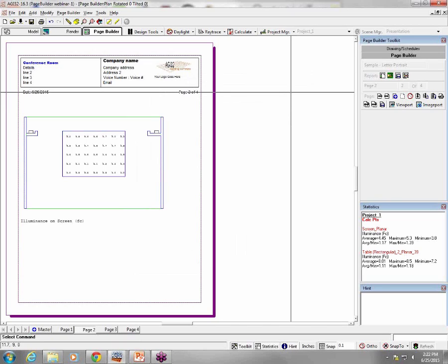Now, as an aside, back when we selected the sample report, if we selected one with a metric size paper, such as A2 or B4, then the text size in that dialog would be shown in millimeters instead of inches. So now I clicked OK and the dialog closed, and the viewport is created. If I don't like its position, I can move it about on the page. I can move it up or down or back and forth if it's not quite right.